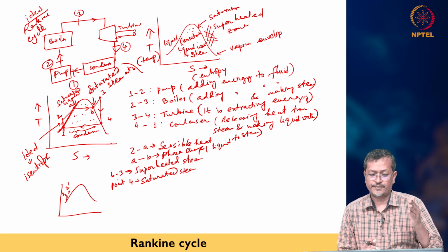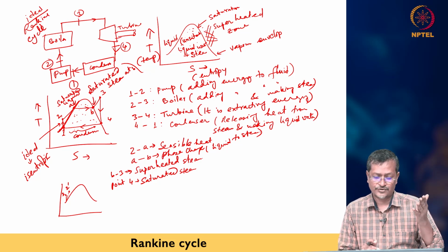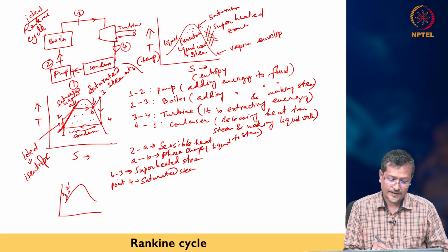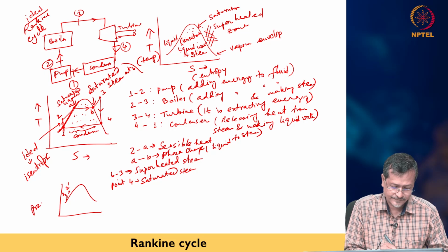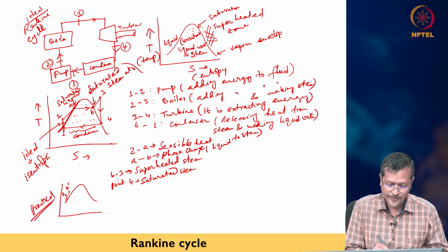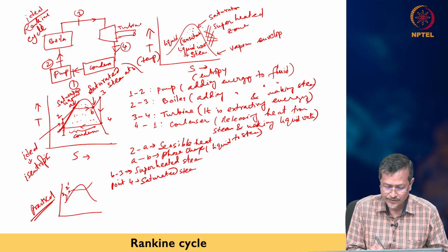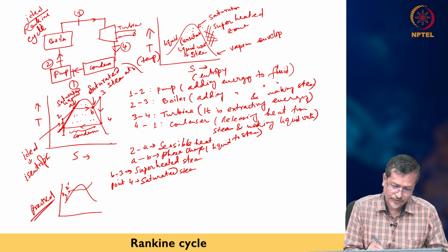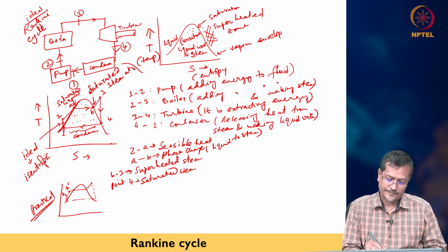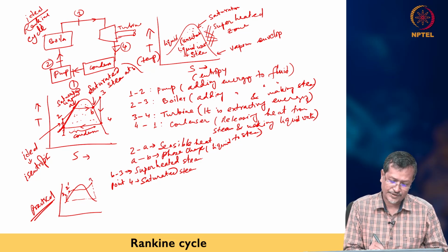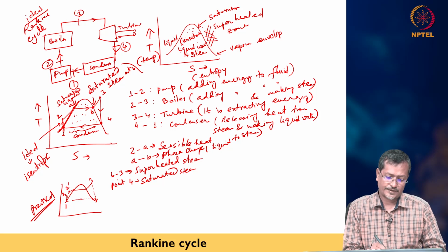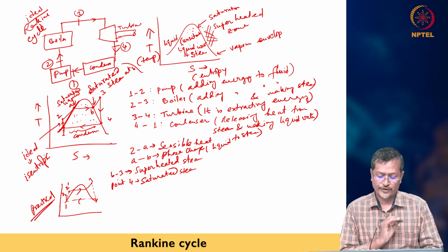Point 2 can also differ because of non-isentropic conditions in practice. So the practical cycle will be like this, it will go like this, and it will give less energy, so 1 2 2 3 4 1, this way it will work. Whenever you draw a figure, you should draw the arrow direction also and write the details of everything.